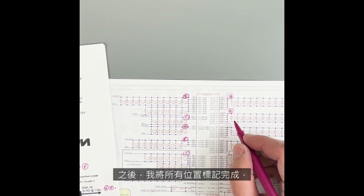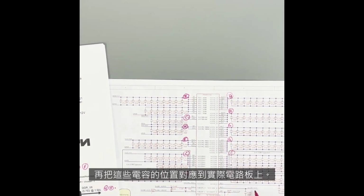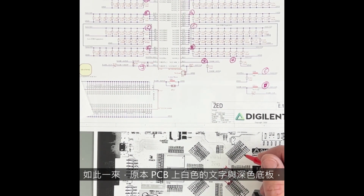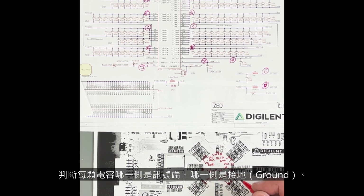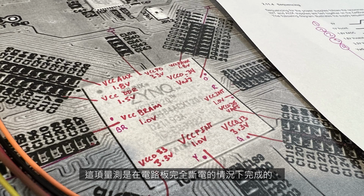So I went and marked them all and identified them, and then took that capacitor mapping and mapped it to the board. Now I took this photo with my phone and printed it out inverted so that instead of white text on the PCB and a dark board, I had a white board and dark text. And this allowed me to go in and mark. Now I did use an ohm meter to figure out which side of the capacitors were signal and which side of them were actually ground, and I did that while the board was powered down.